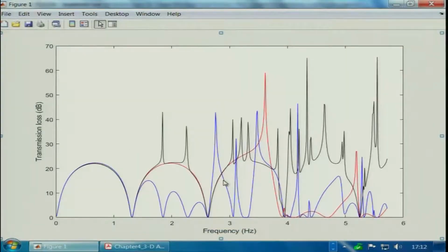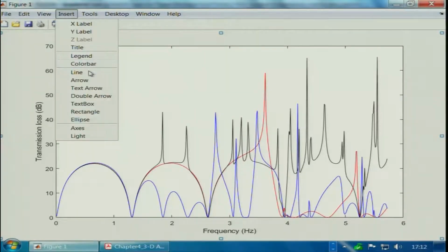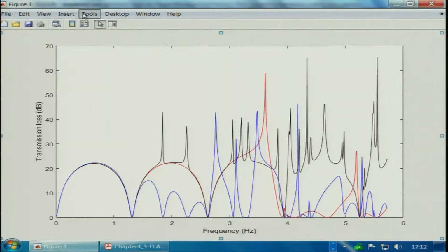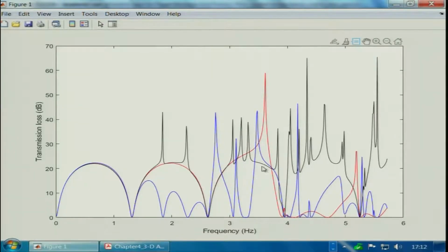Well, it fails even faster, at a much earlier frequency. At what frequency does it fail? There is a collapse of the dome trough pattern. At least the dome trough pattern you can get only at isolated frequencies, where you are getting a problematic thing. The muffler was transparent. The good thing about the dome trough pattern is that at least it shows where the problematic frequency range is. But when this fails, you not only get a collapse, you get a lot of troughs, and attenuation is also completely annihilated.